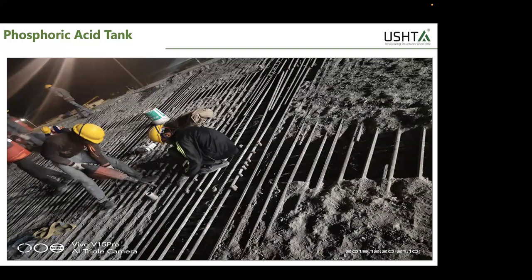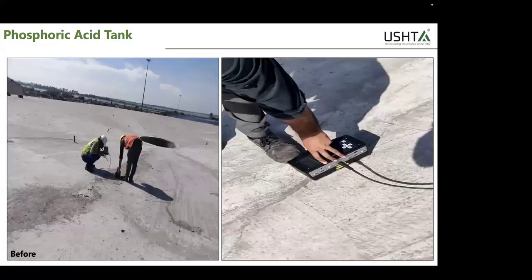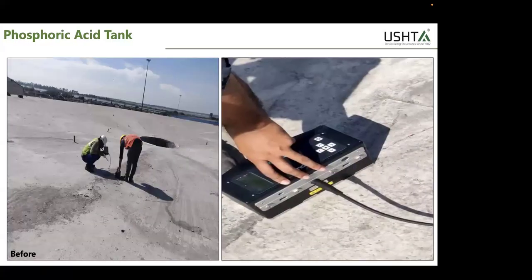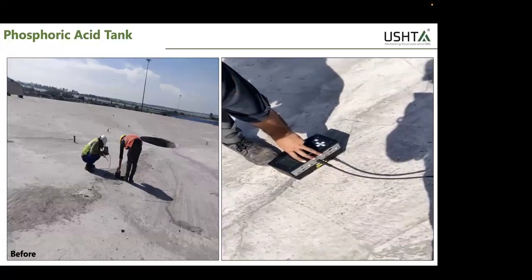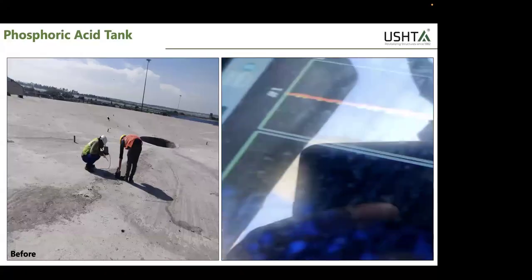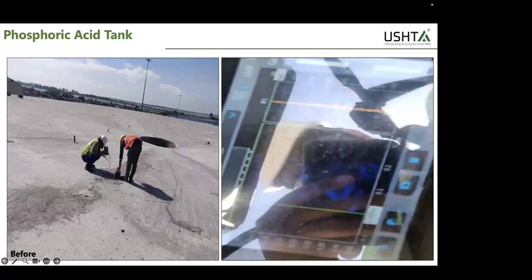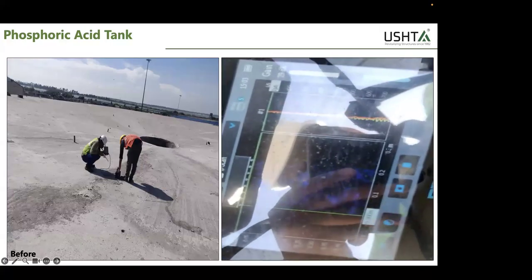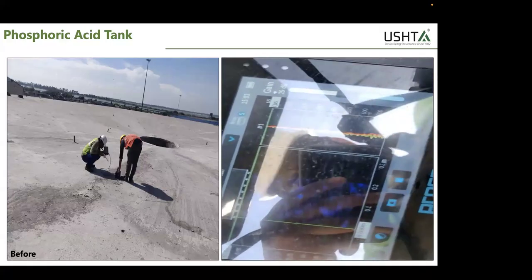So what we did was, large voids were grouted by micro concrete. Small voids where honeycomb was there were grouted by microfine cement. And the top layer was replaced with concrete. Later on, we did complete tests again. In that also, we found 5 locations which were regrouted. So yeah, any questions on this, or should we move to the last one?